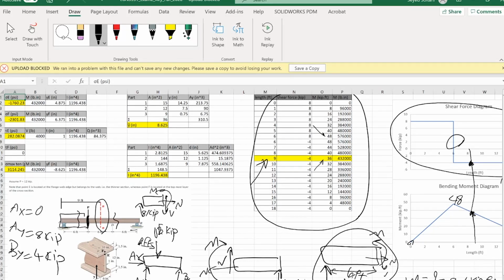All right, but before we do that, keep in mind that we need to calculate the bending stresses as well as the transverse shear stresses, right? So if you start with the bending stresses, negative My over I, M, which is being determined based on this diagram, and this is the value for it, is only one variable out of 3 that we need to know, right?